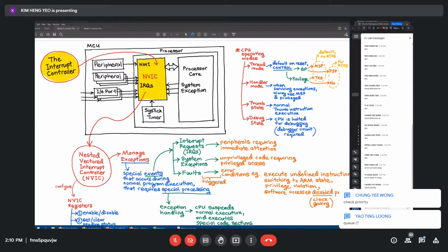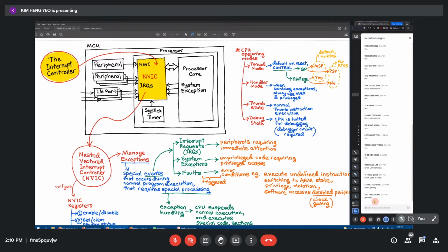Q. Q means basically in a PIC microcontroller, if the processor is currently responding to an interrupt, that means the processor is executing code in the interrupt service routine. Another interrupt comes along, you say Q, right? Yeah, that's correct. The idea is correct. The processor won't respond to that interrupt until it is done with the current one. So we say the other one is queuing, or a better word is pending. The interrupt is pending, is waiting.